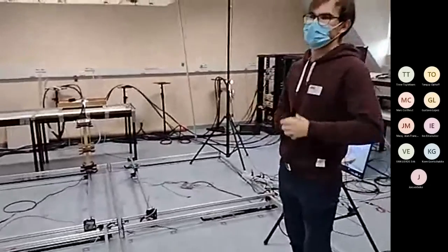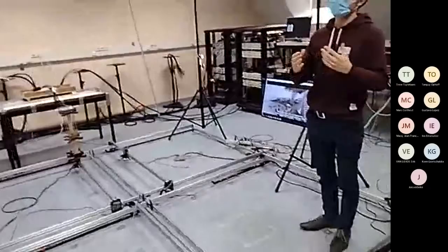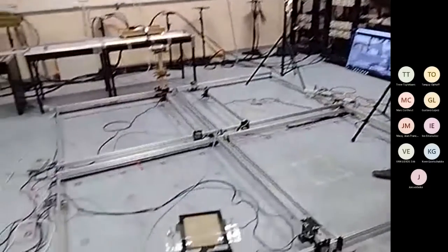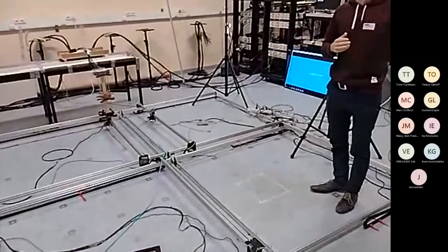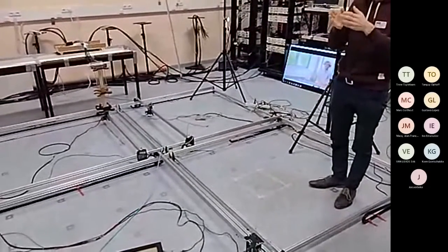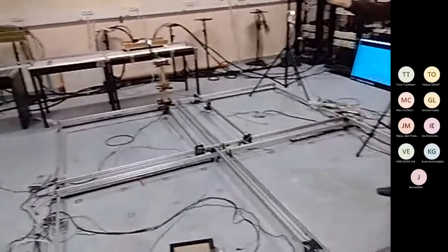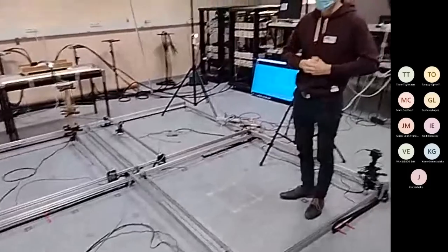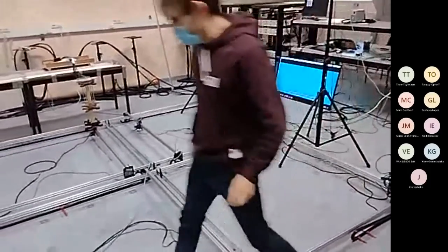One of the properties of millimeter wave is that it has large path loss, which means that if you send a millimeter wave signal, the energy in the signal gets lost very quickly. That's why we first of all need highly directed beams to compensate. We can get more gain in one direction, so we compensate a bit for the path loss. To show this, for example, I can stand in between the signal.